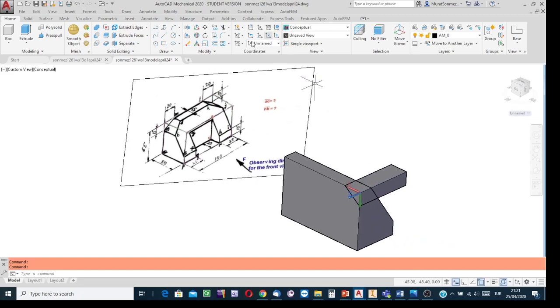Mirror copy process. Expand the modifier panel and find the process button. Click. I started mirror copy process. The system is asking me which entity to copy: this triangular prism. Indicated with a click, and then press enter. The indication stage is endless, so need to click the enter key.